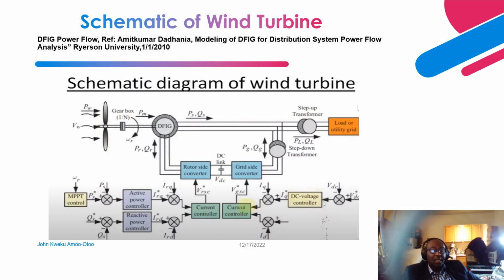Now let's do a deep dive into the controls, right? Okay, so you can have an active power controller or a reactive power controller. So these are the outer controls that we have. This can be integrated through MPPT, and MPPT is maximum power point tracking.